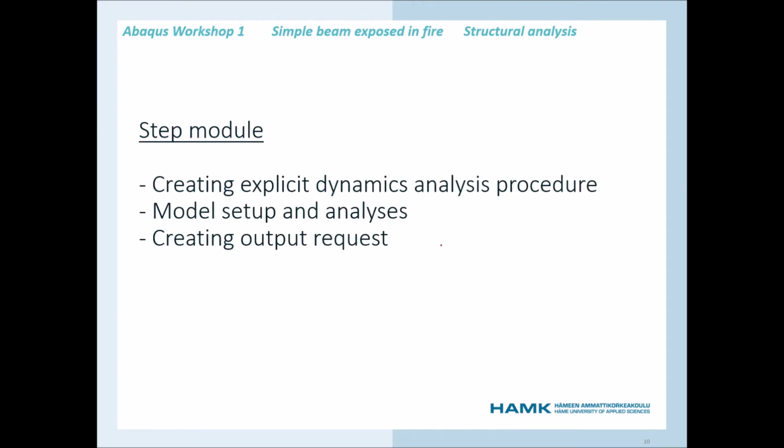Next we need to go to the step module. In the step module, we create the static analysis process using explicit dynamic analysis procedures, and then we have the model setup and analysis, and then create the output request there.